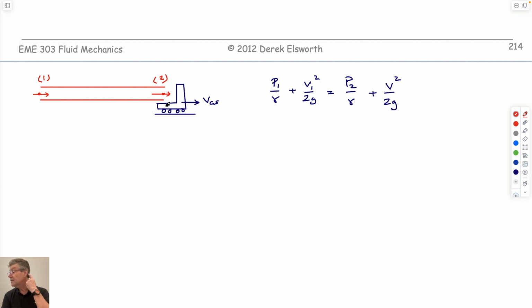So we did the example for the truck on the SFO apron being blown off into the bay. And we talked about what the force would be on this. We know that the pressure upstream, because pressures act in all directions, and it's coming out, it's in the air. We don't know what this pressure is. We know that this is a static velocity because it's coming out of the fire hose. But instead of having this truck static, let's have it moving at the velocity of the control surface.